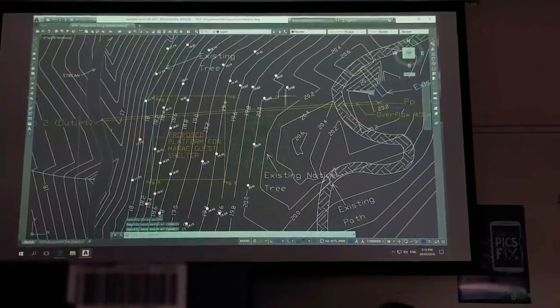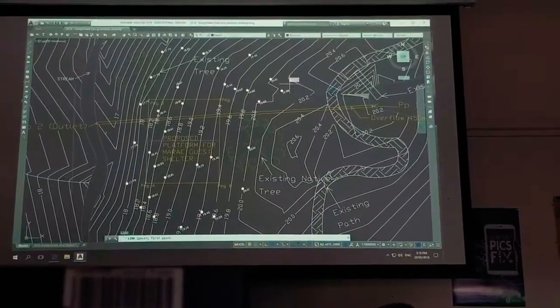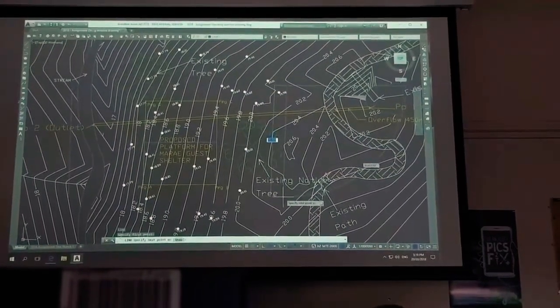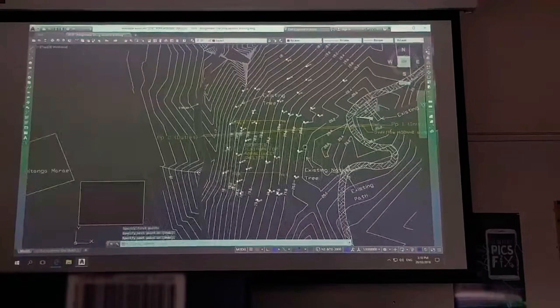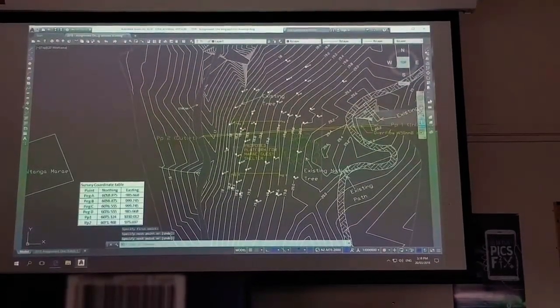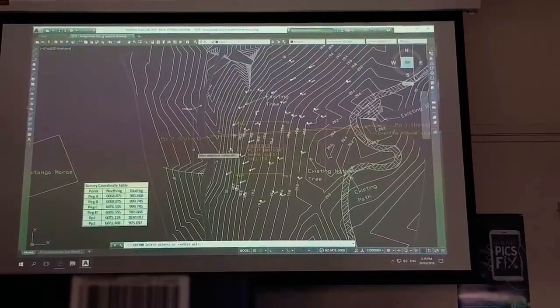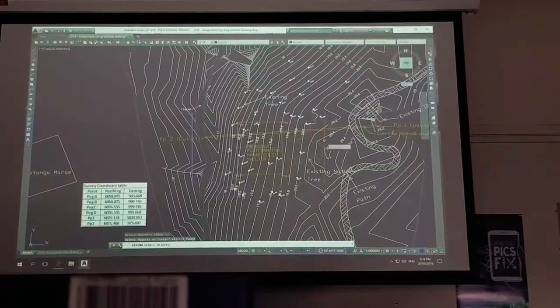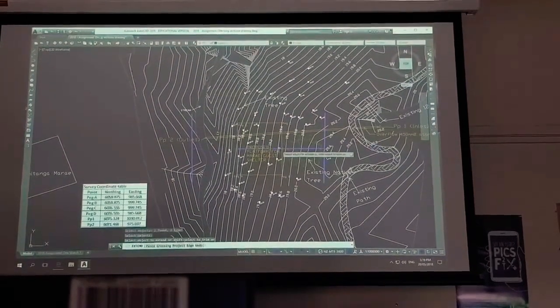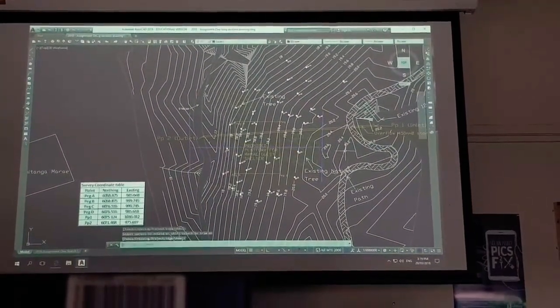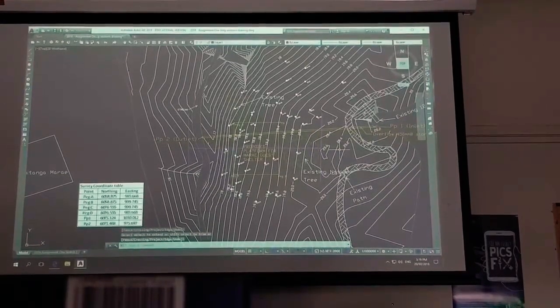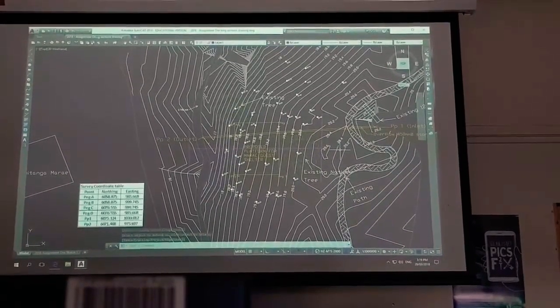On this side it doesn't really matter, but I would very much like to get that tree in, if I can. So about there. Then I'll use the extend command, click on that line, and then click on the end of here, and you'll see I've extended my extension line through to the pink lines.